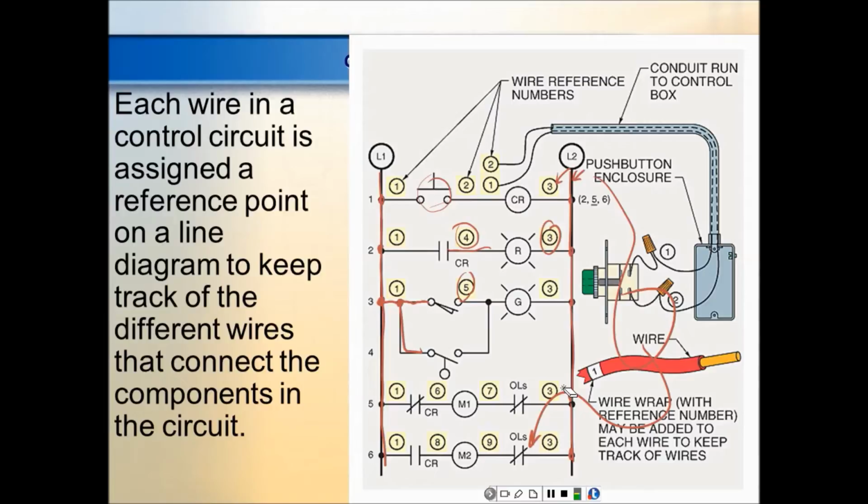But usually at a big plant, like a commercial plant, they don't put any numbers on any wires. They number the terminals that these things go to. Y'all know terminals, right? So they'll go to a terminal strip, and then the numbers will be on the terminal strip. You get into a big plant like US Steel, all the wires are black. They run black. Because that way they can buy the wires in gross, right?